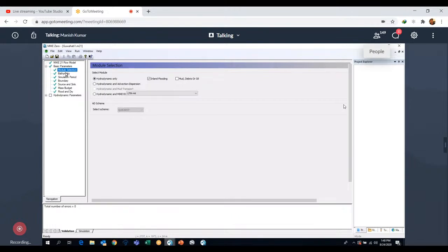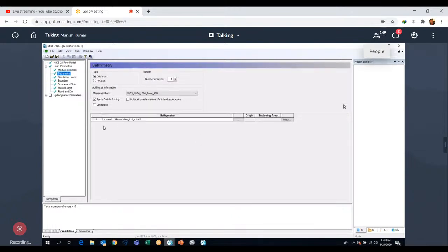You have a choice. You can use both types of model. So here, for the MIKE 21 model, the data information required is huge, but model establishment is quite easy, in the sense that you only need this DFS2 file, meaning bathymetry information, like this.